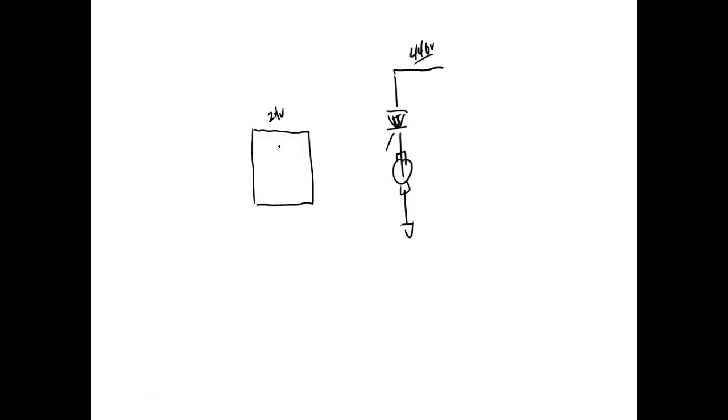Understand? So what we do is we isolate the power circuit from the firing circuit. One of the methods we use is a little gate transformer. In fact, it's called a pulse transformer. They put dots on these things so you make sure you hook them up right. Then you would take this and hook it up there, and take this and connect it there. So what happens, we know a transformer won't pass DC, but it'll pass a pulse. So when I fire it, it would pass it through there.